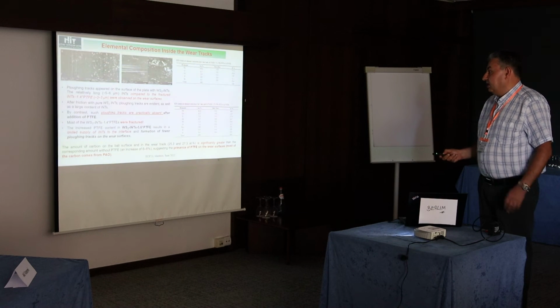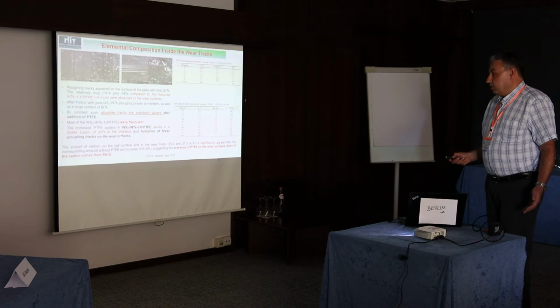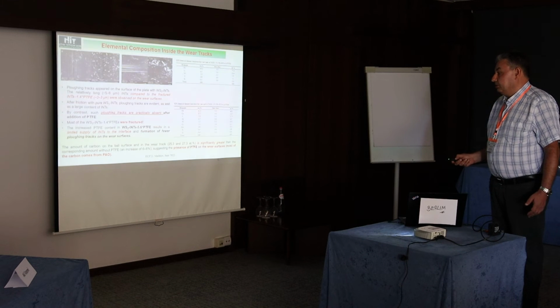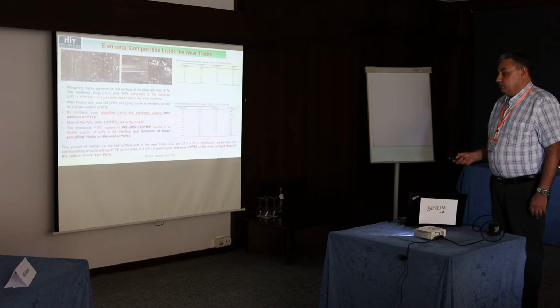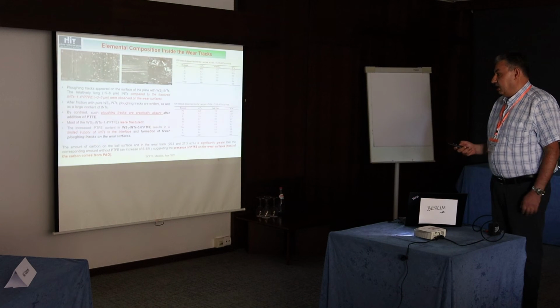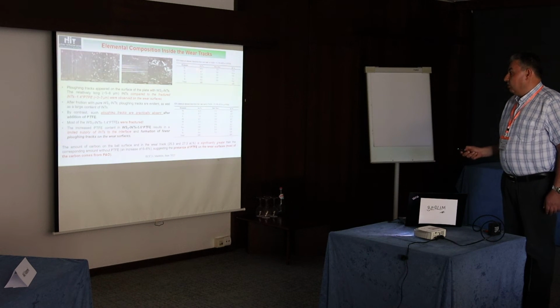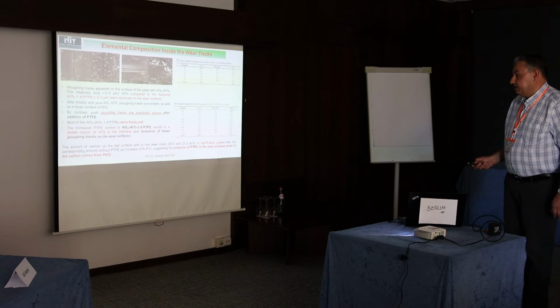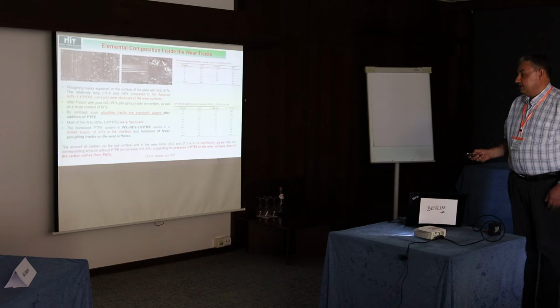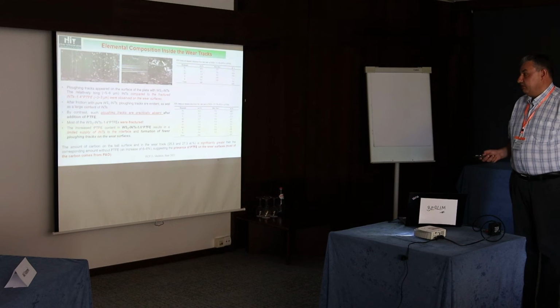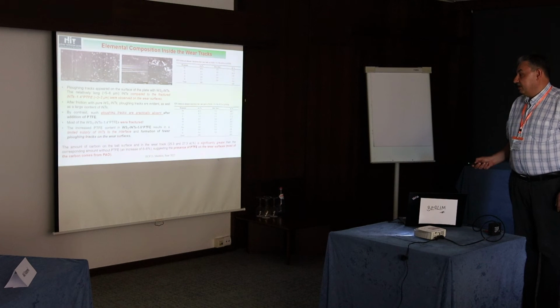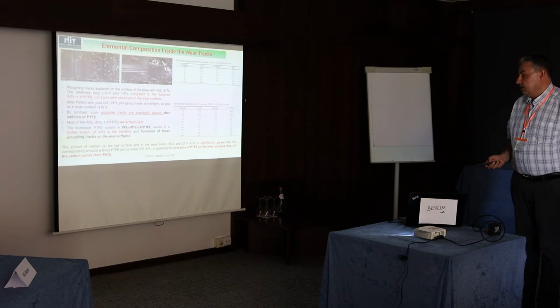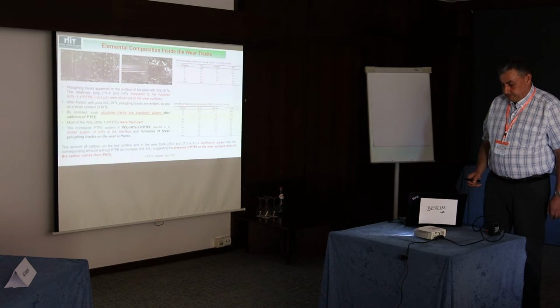the friction coefficient. And on the contrary, when we have too much Teflon, then there is limited supply of nanotubes to the interface, and again we have some increase in friction coefficient and wear spot size. Also, the elemental analysis by EDS shows that there is increase in carbon inside the tracks. Most of the carbon, of course, is not from Teflon, but from the oil, but the increase is entirely from Teflon, as we don't have any other source of carbon during the process.